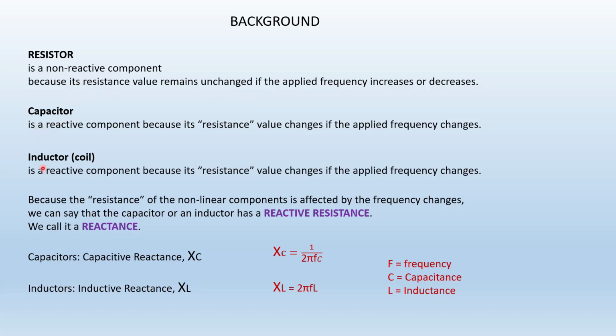Now, capacitor and coil. A capacitor is a reactive component because its resistance, and I put resistance in quotes here, we'll get to that, its resistance value changes if the applied frequency changes.